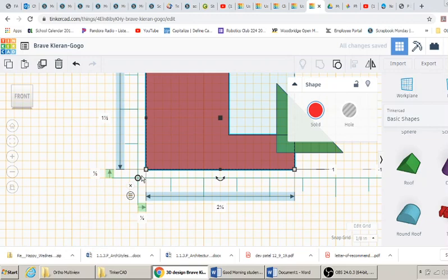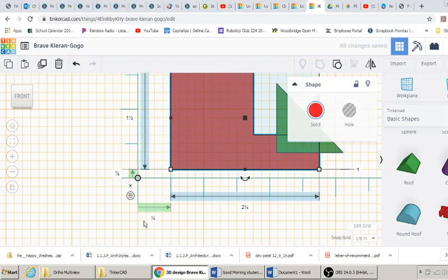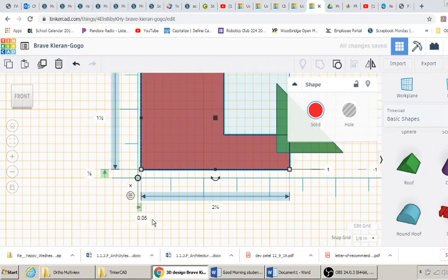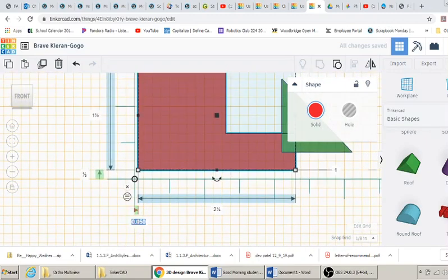Right now I moved it over 1 square. You can see it says 1/8 inch, 1/8 inch. In fact, I could change that to 1/10 of an inch if I wanted to. See that? I could change it to 50 thousandths. Oh, that's a 1/2 inch. I forgot the decimal point. I put the decimal point. I forgot the 0 after the decimal point. There we go. You can see a precise distance. So the ruler tool is very helpful.